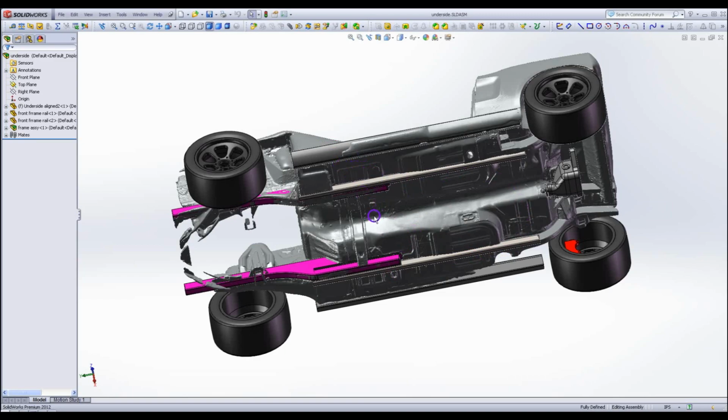But when I tried to import the step file, it was just too big. SolidWorks just crashed. However, I can take this file from my 3D scanner and put it into FreeCAD. And then in FreeCAD, I can get it aligned up, put the center point where I want it, and line up the axes where I want it. And then if I import that into SolidWorks, it's fine. It's a little bit slow, but it's fine. And then I save that underside as an assembly. So I have an underside aligned.